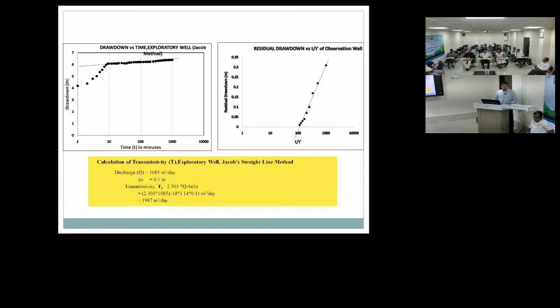No, fracture depends on the hard rock area. We have done here in Tetlebori, I have told you. Recently we went near Hojai, Udali. There it took us around 3 hours. The static water level was around 22 meters, and after pumping for 1000 minutes, the water level went down to 39 meters. So from 39 to 22 meters, it took us around 3 hours.